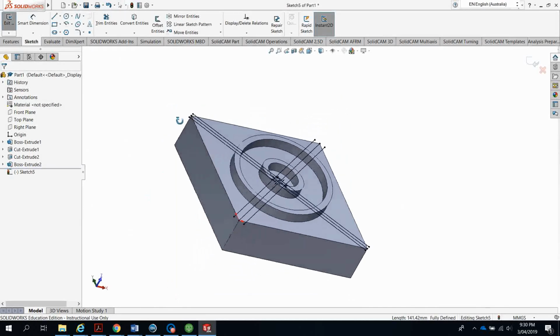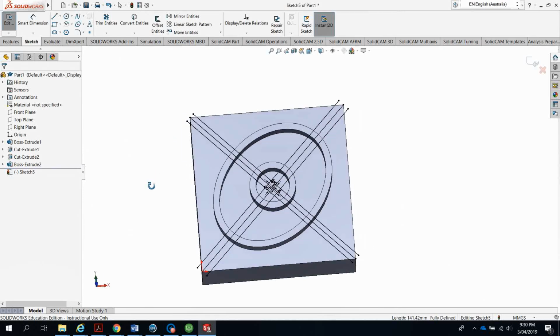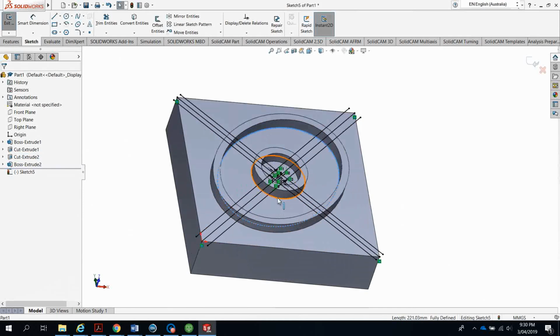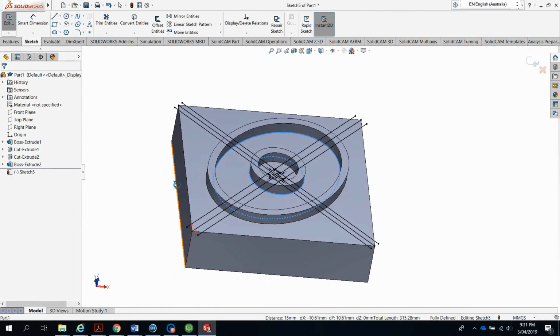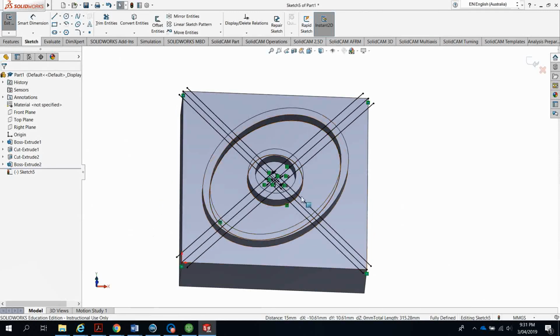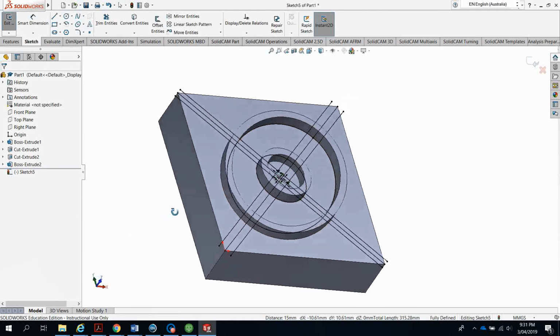Now this takes us nowhere at the moment. The best thing to do is the following: click on this surface and choose this edge and the inner edge of the circle. You have to click using Control, and you are going to choose both. Convert these entities. That means we sketch a line on the edge of the elliptical and the edge of the cylindrical shape.